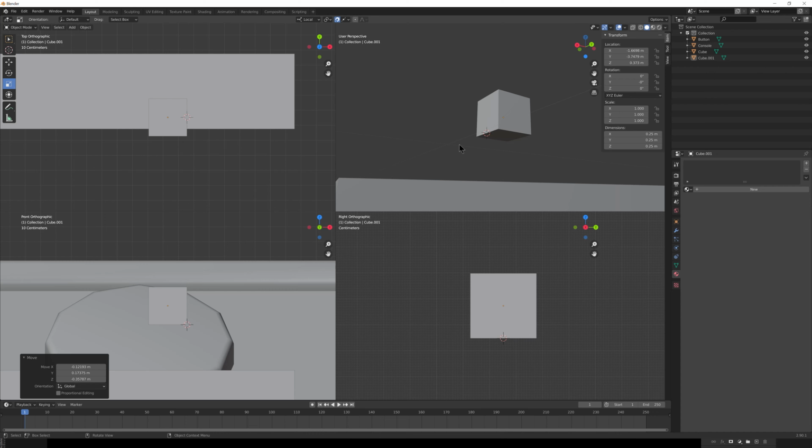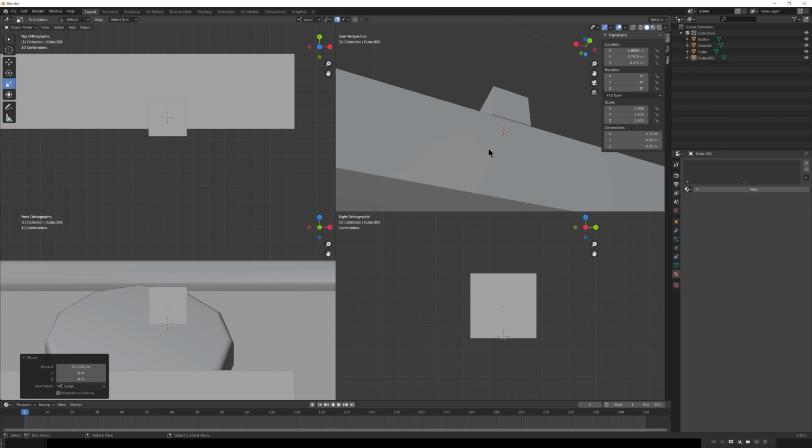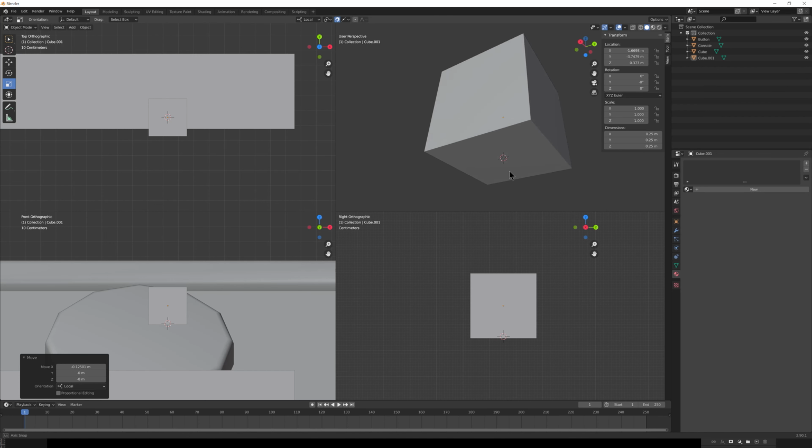So if I go ahead and hit Shift, and then of course right click over here, what we want to do now is snap over to this side. So if I let go of the Shift key, and we note that that is probably going to be in the Y and X axis over here, we can have this move over to the side, and if we select this part over here, we'll notice that 3D cursor is actually going to snap into this location with respect to this side area.